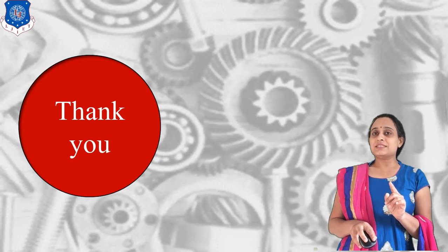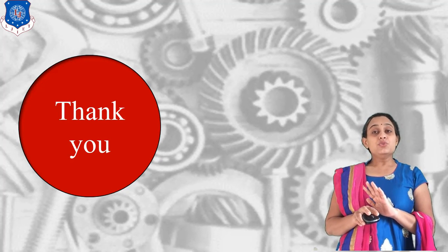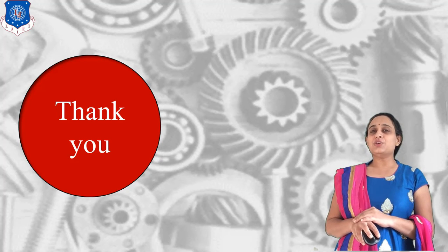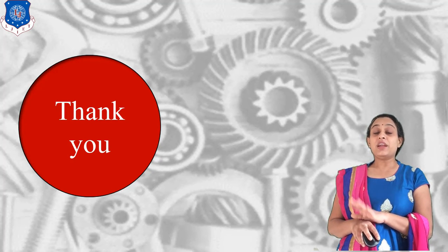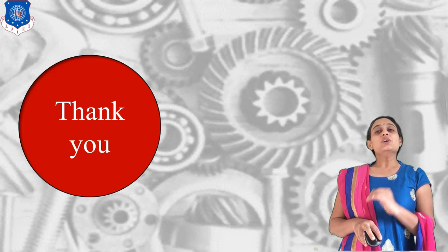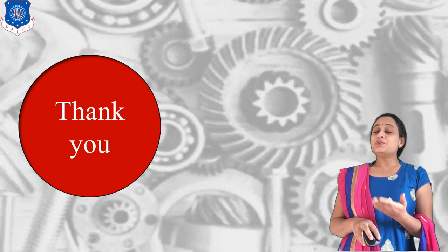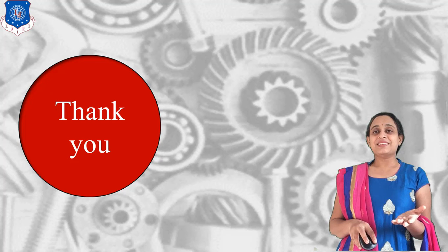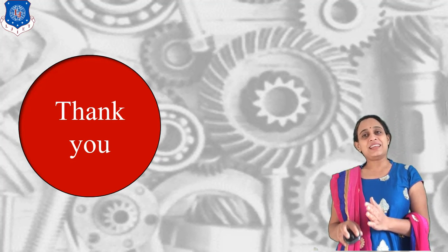So for our system, for the V engine and for the radial engine, no couple is generated. If you remember our V engine theory, we only solved our primary and secondary forces. We did not discuss any couple value, right? So in this case, couple will not be generated, and if we reduce the couple effect, we will automatically balance our machine. So here, this is our theory of the direct and reverse crank method.